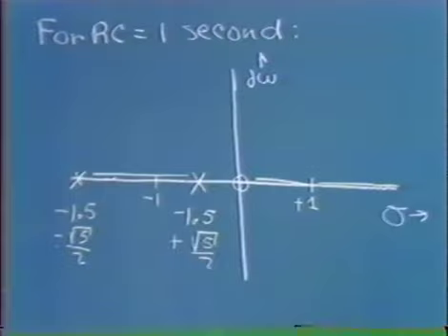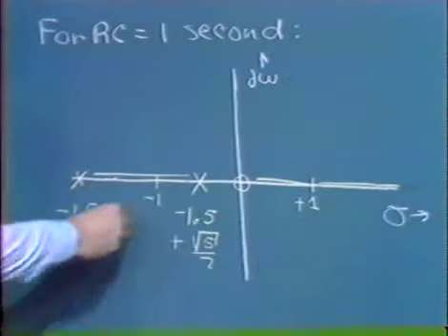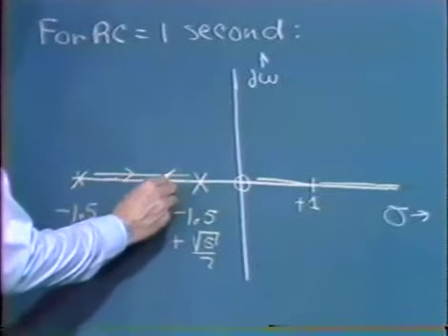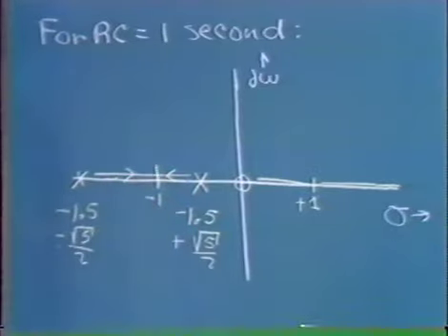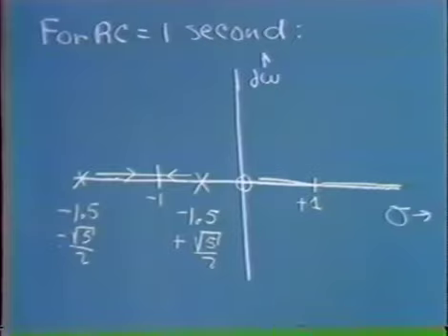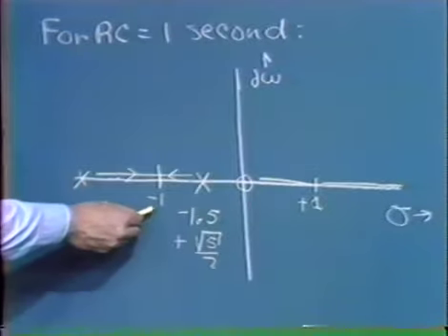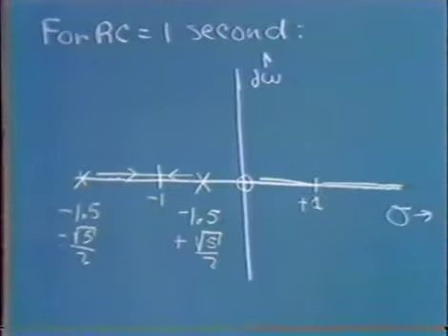And again, we can make appropriate modifications to the other rules. We find out that if we evaluate the root locus diagram for this positive feedback system, these two branches simply come together and break off the axis. There's a rule that tells us where the breakaway point occurs: factoring the characteristic equation, or the loop transmission, with respect to s and setting that equal to 0, we find out that the breakaway occurs at s equals -1.